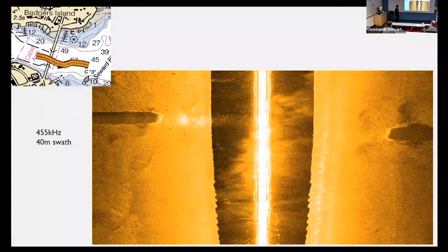One other image I wanted to share is a record gathered underneath the Memorial Bridge in Portsmouth. I thought this was impressive for a couple of reasons, in that it was impressive that the navigation record wasn't corrupted by the multipath effects of the bridge. We also see really nice sand wave details here. We see the main piling structures for the bridge on either side of the main span, and then we even see scour around those pilings.